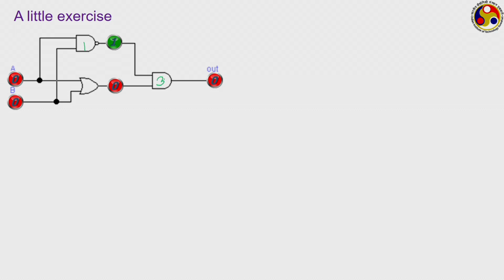This gate number 3, this is an AND gate, and whenever we have this dot or whatever this extension in front of an AND gate, that represents a NAND, which basically reverses the output of an AND gate. And what about this number 2? This is an OR gate. So one particular combination of output is given. Let us try to form the truth table using the other kinds of inputs.